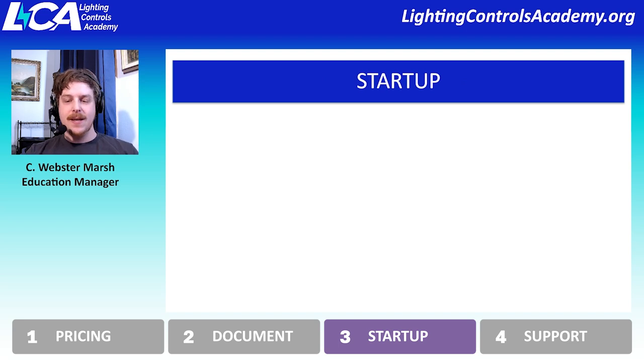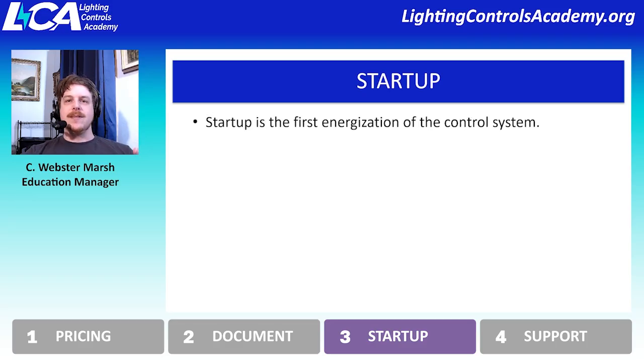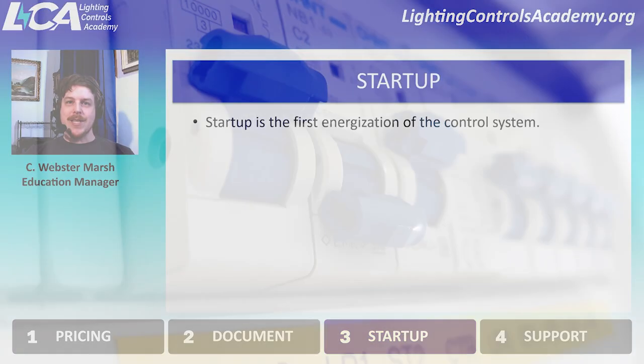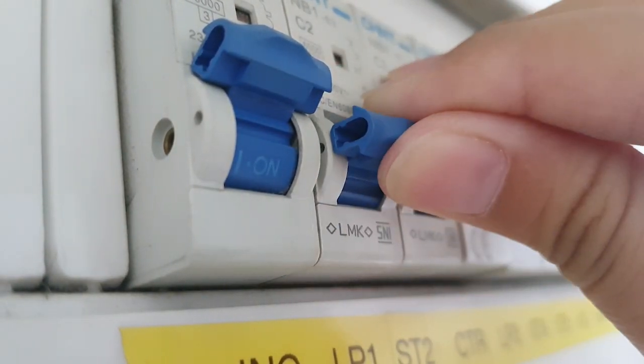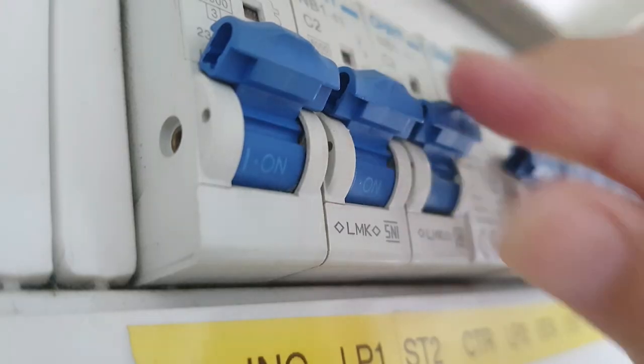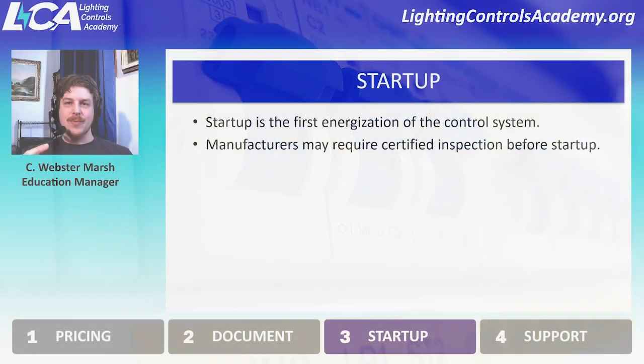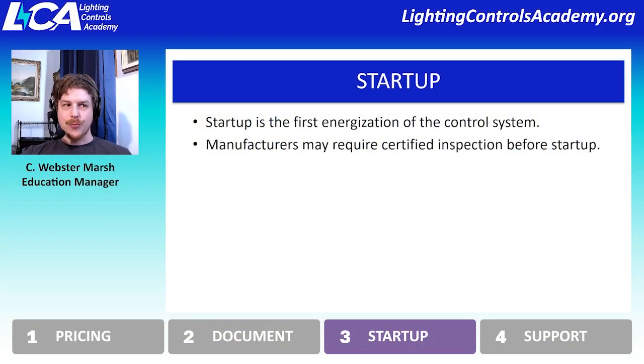So startup is talking about when you first energize the system. So when you first put power to the devices. And sometimes manufacturers are really strict about how you go through the startup procedure, primarily because they've been burned in the past by having the contractor either not set it up correctly, not wire it correctly, and they turn the energy on and they fry a number of devices because they were miswired.